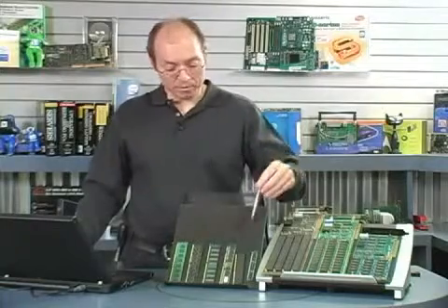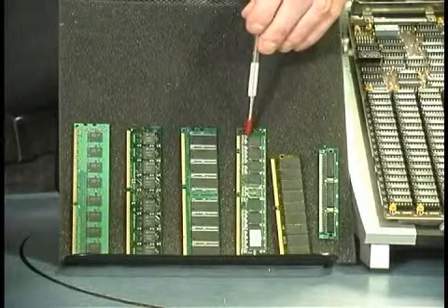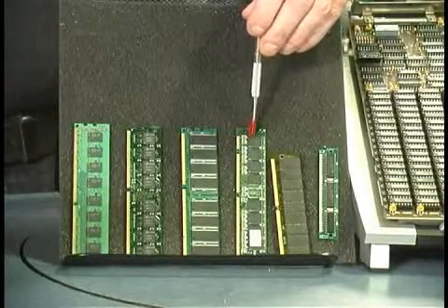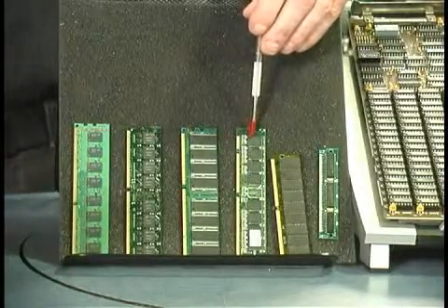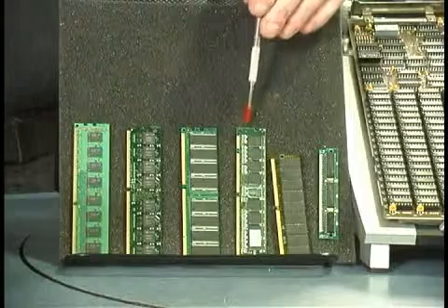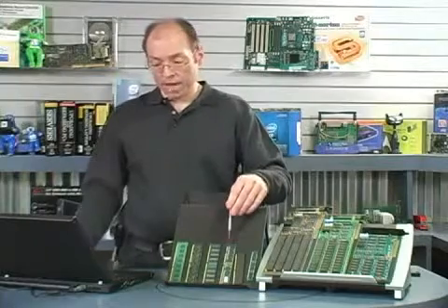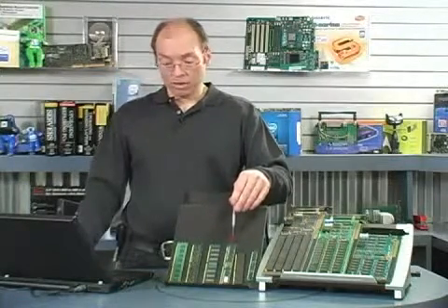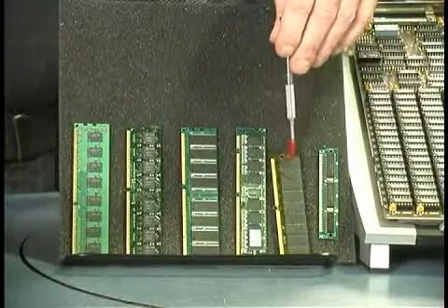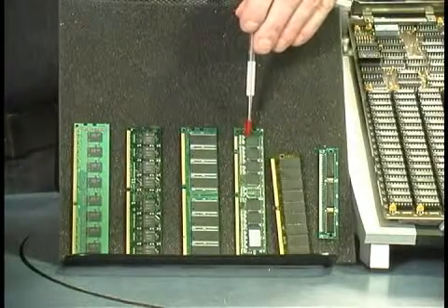Well, we had a breakthrough in memory when this type of module came out. This is known as a DIMM, and the type of memory that goes on this DIMM is called SDRAM, synchronous DRAM. The synchronous was important because that meant it ran in sync with the motherboard. This stuff was available at speeds up to 133 megahertz, which matched the speeds of the motherboards and the chipsets at the time. Now, the SDRAM was popular between 1998 and 2002, and it replaced these 72-pin SIMs. So from 1998 to 2002, we had a lot of systems using this SDRAM.